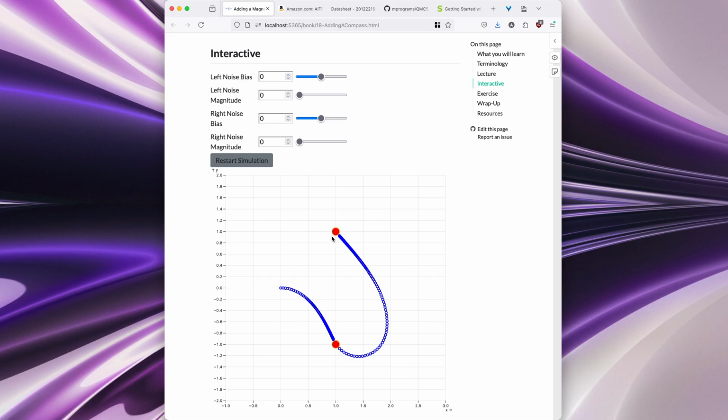Currently, we've been assuming that our robot follows the exact path it thinks it follows. But forward kinematics doesn't take into account errors that can build up. In fact, if you were to take the wheels off of your robot and run the forward kinematics or the position control process, it'll happily drive itself to some location without moving anywhere. And the error would be whatever the distance is from the origin to that final location.